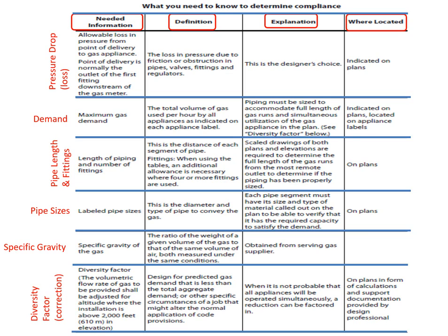The specific gravity of gas, the information can be found from the gas provider, whether it's a utility, whether it's a LPG system, things of that nature. You can find this out from the gas supplier. This enables us to properly integrate this specific gravity into the design of the gas piping system.